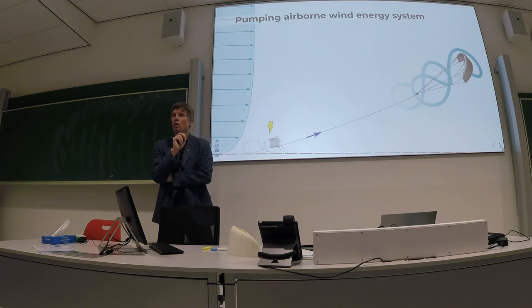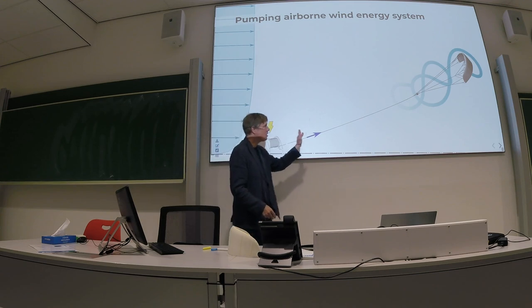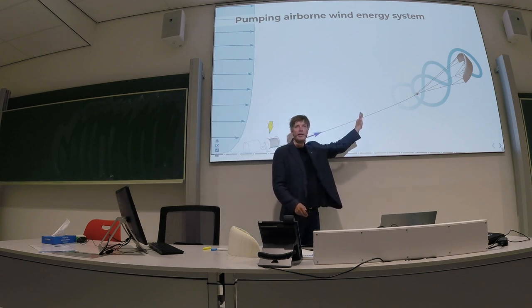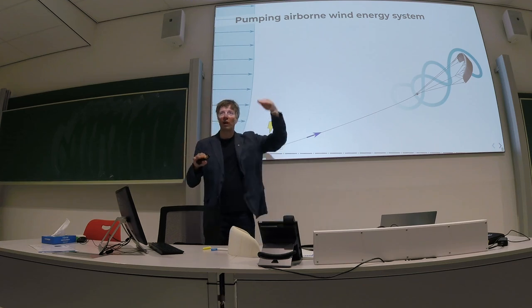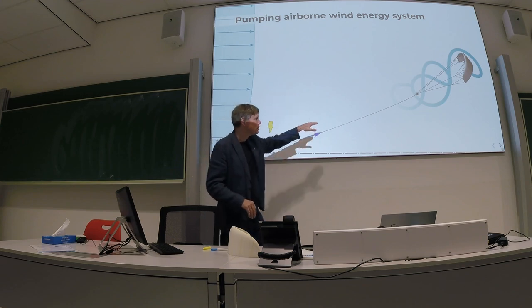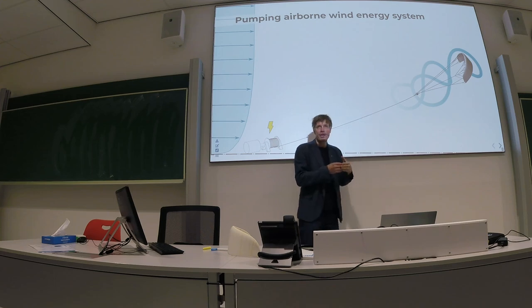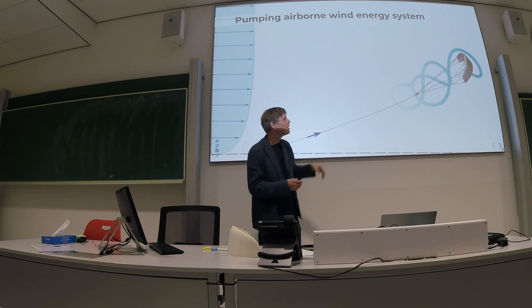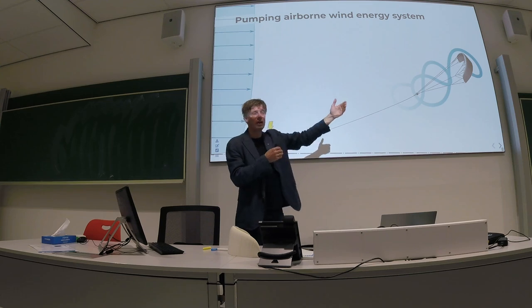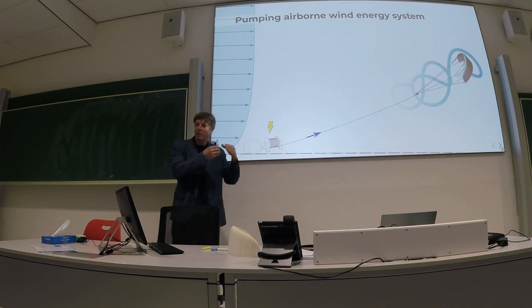This is a core optimization issue in our field, to determine exactly what's the minimum tether length we need. And normally this is a pure safety constraint. You want to have a certain distance from the ground. So we have a Z-min that we need to maintain. There we can, depending on the elevation angle, derive a tether length. And then we have a maximum tether length that comes from whatever tether we have on the drum. And there is an optimum of how much you reel out.